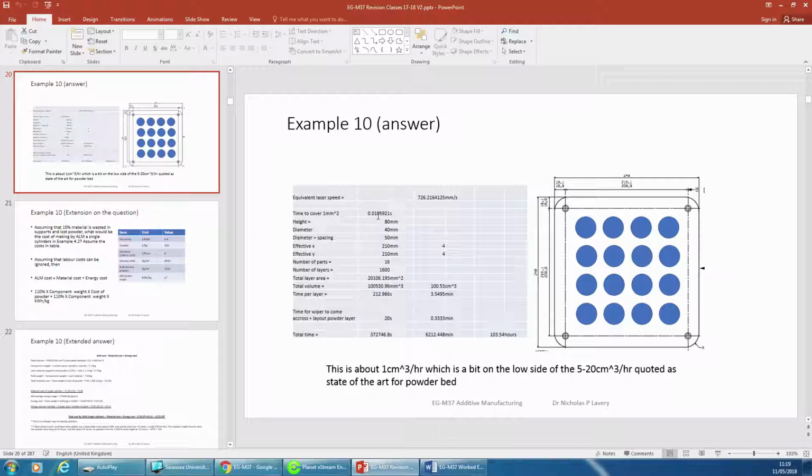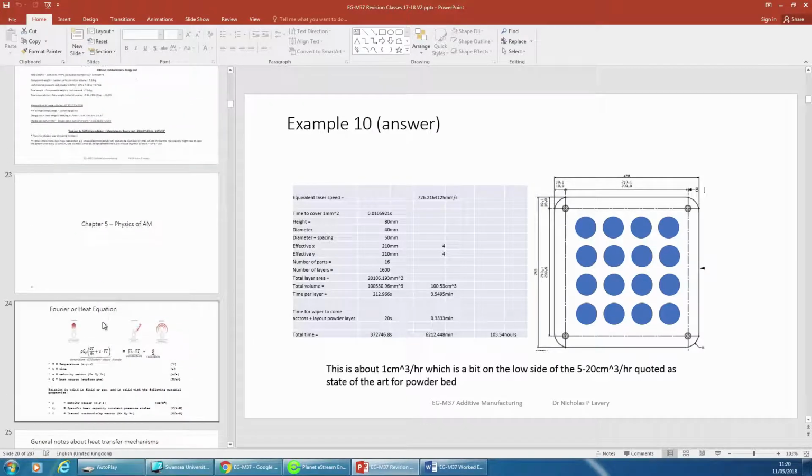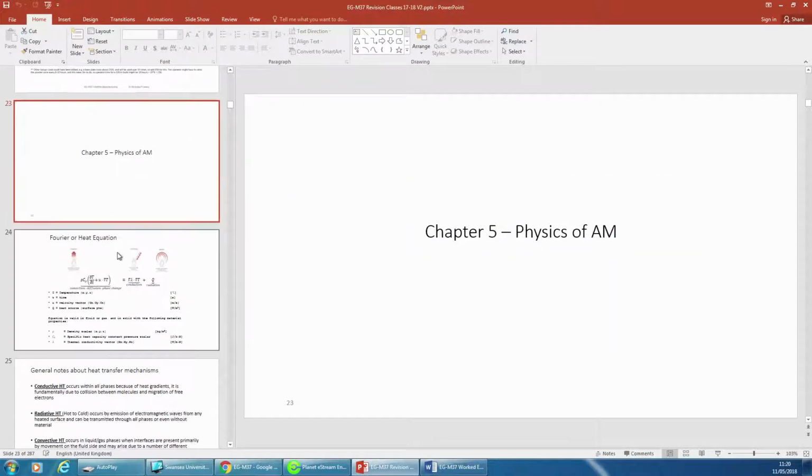It wasn't really about that. It was just about how you would approach putting something in. Potentially that part could have been much more complex, but then you could have a cylindrical envelope around it, so you would use that as a sort of first estimate of where you'd locate it. Obviously, Quant-AM does all of this for you now, but it's worth knowing sometimes Quant-AM doesn't get it quite right, so you need to go over the top of that.